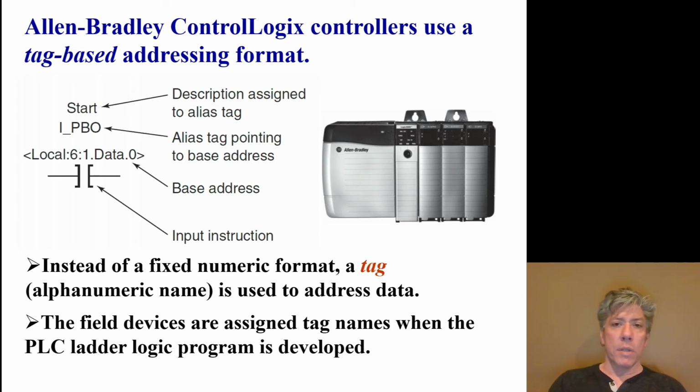Now, of course, in PLCs there's other memory as well. Allen Bradley, for example, has files that are supposed to be all integers, or that are supposed to be all bits, or that are, I'm trying to remember what else they've got. They've got a timer file, a counter file, and it's a powerful language set because you can access these things at the bit level or the word level and do some interesting things with them.